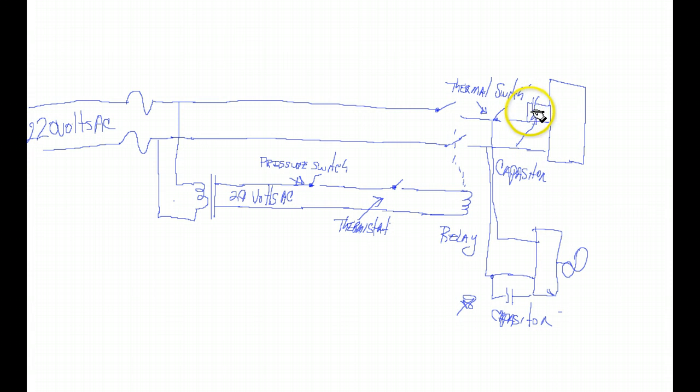If the capacitor is bad, the compressor will hum but won't start. So if you get a humming over here, and the compressor is not running, that's an indication that you've got a bad capacitor. In addition, the fan is tapped off